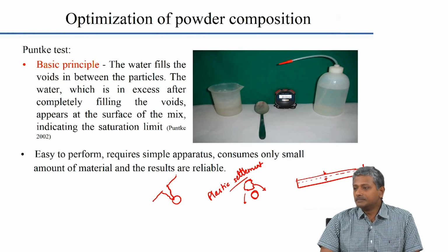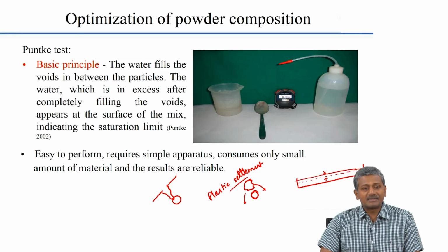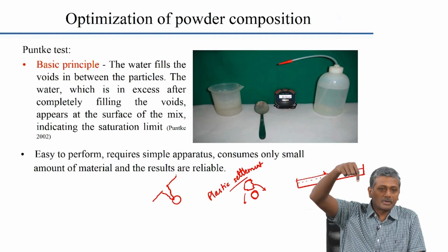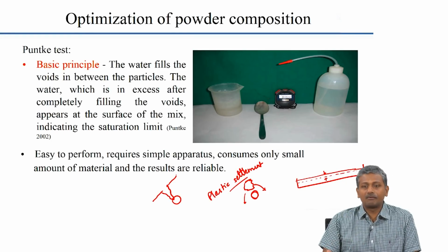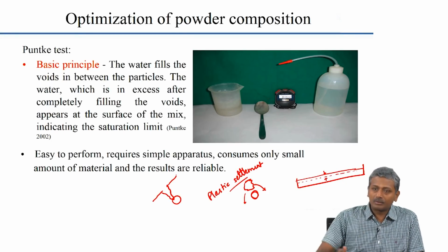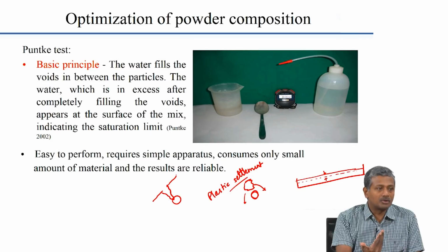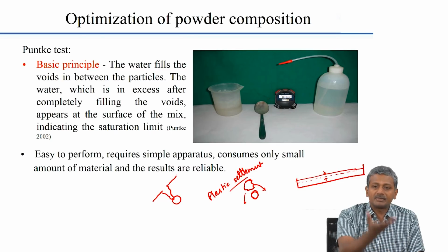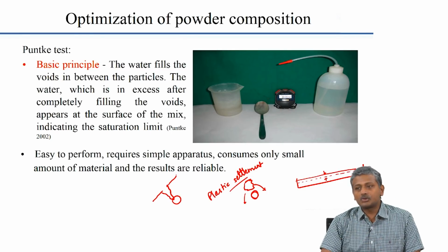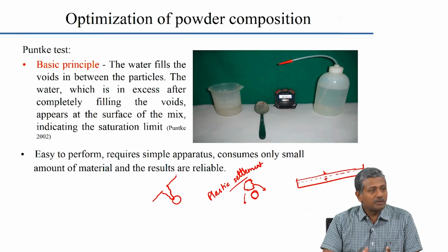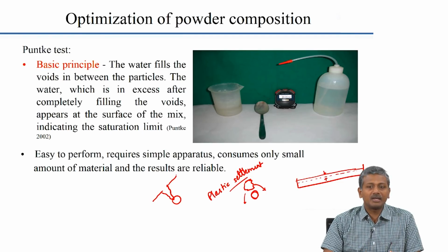Now, for a column, how will you pour SCC? Yeah, you probably cannot pour it from the top because it will cause segregation. SCC is highly flowable. So, you will input the concrete from the bottom, you pump it in from the bottom and it just goes up, and that is actually an ideal situation because it will completely fill up the formwork without any air gaps.